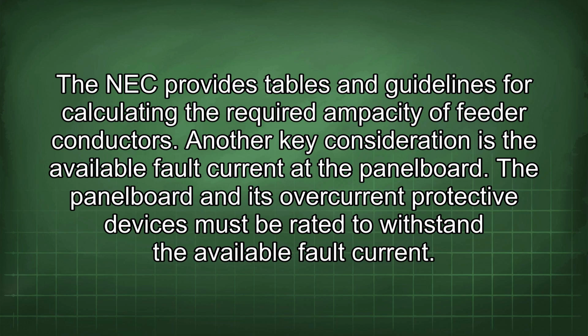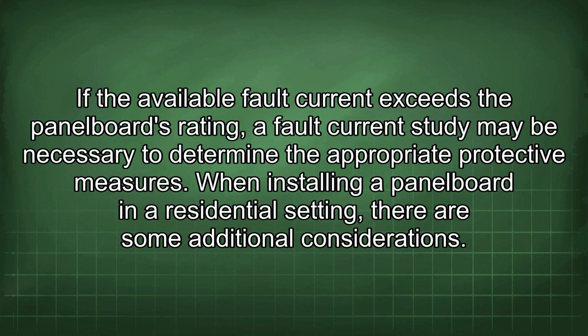Another key consideration is the available fault current at the panel board. The panel board and its overcurrent protective devices must be rated to withstand the available fault current. If the available fault current exceeds the panel board's rating, a fault current study may be necessary to determine the appropriate protective measures.